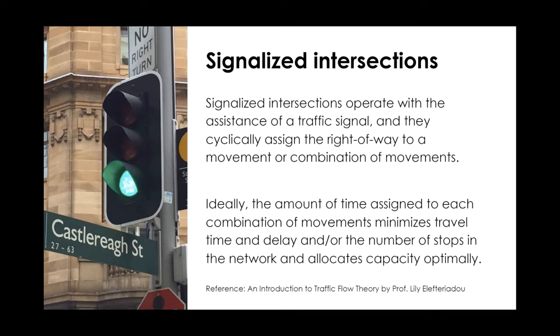So when it comes to designing the signal intersection, other than the geometric aspect of it, that sure, we look at the geometry of the intersection, how many lanes do we have, what movements do we want to have on the intersection, do we want to have a right turn or left turn lane specifically, what kind of movements do we want to group into each other.